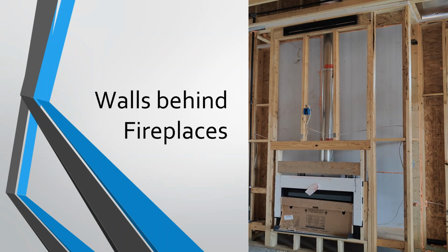Sometimes it's just left open. Maybe it's capped at the top, but it's not insulated in the back. Now they're going to insulate the back, but now they need to put T-ply in front of it, but they don't want to, so they try to put netting. You could do the front walls, but now you have to do T-ply on the back, and then you have to insulate the inside, and then you've got to put sheetrock on the front. Either way, you must have a continuous and aligned thermal boundary, including the air barrier and the thermal boundary making up the thermal envelope. So it never surprises me to see they leave this open.